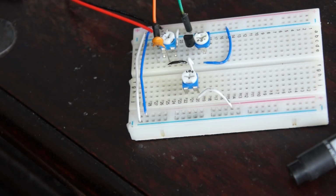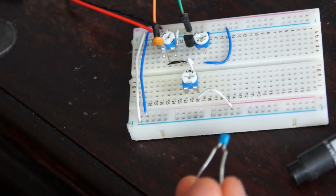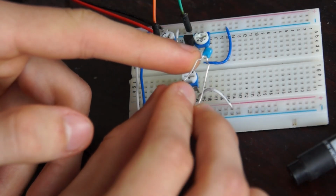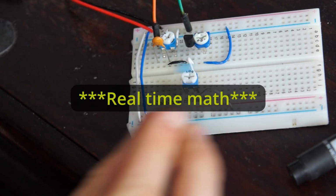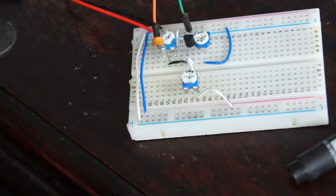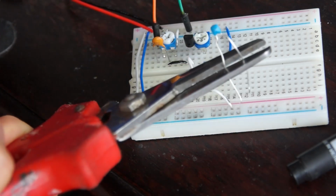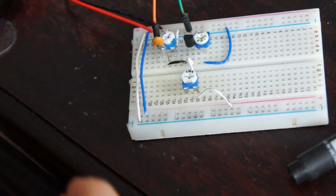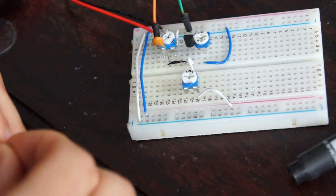So the only thing we need now is an output capacitor, and I'm going to use this 224, which means 220 nanofarads. Going to snip off the ends, and this has to go from the collector to our output. So I'm just bending it in shape.